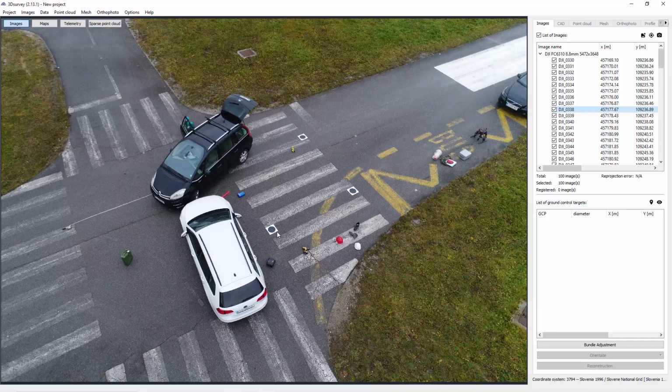With this approach, we eliminate these costs. More police patrols can have that kind of system, so you just need a drone and additional knowledge of how to orientate it without measuring with a GNSS device, and it also works. Important is that you place those targets on a horizontal level, so you need to find an area which is horizontal. Targets need to be perpendicular, and we defined a 3 meter distance between them. It's good enough for us to deliver accurate data. Nevertheless, if you have a GNSS system, or, for example, a laser scanner, and you do a scan in addition, you can use all that information to do the orientation. But today we will do it with this approach. You will see this a bit later on.